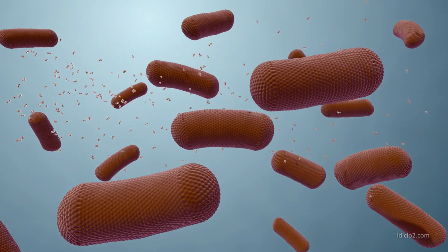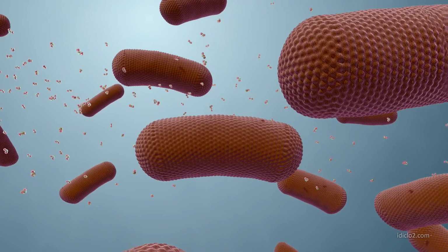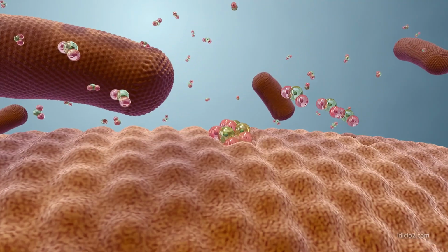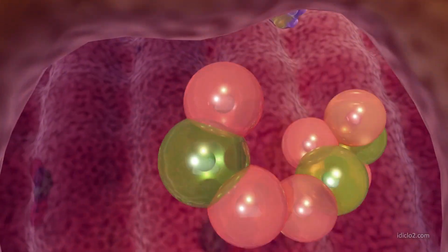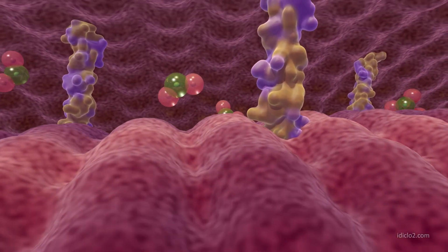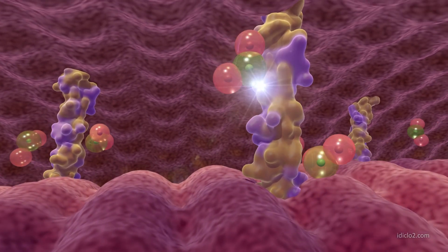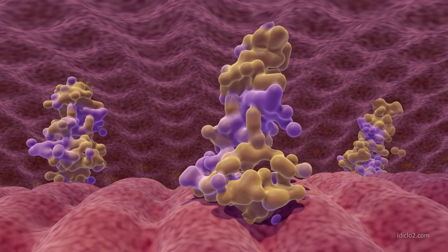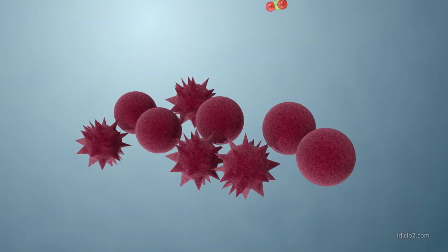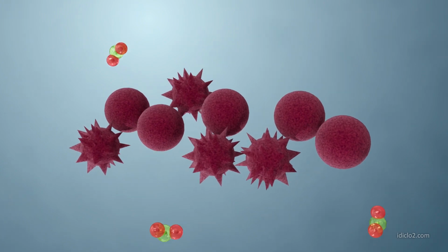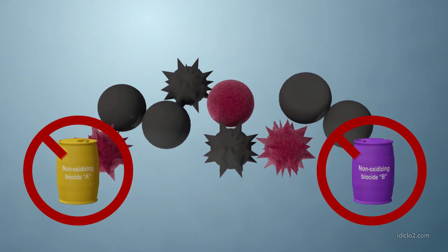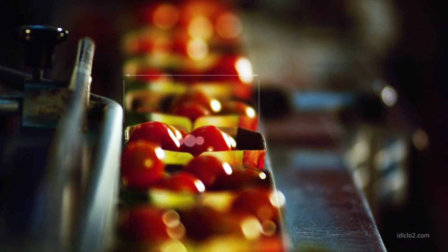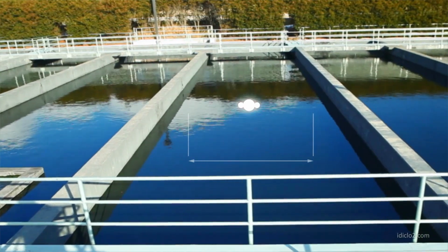When treating with ClO2, microorganisms typically found in industrial and municipal processes cannot alter their structure or develop immunity. ClO2 rapidly diffuses through cell membranes, oxidizing critical proteins and amino acids inside of the microorganism. These reactions disable cell metabolism and prevent microorganisms from developing a resistance mechanism. The use of chlorine dioxide eliminates the need to alternate biocidal chemistries in critical applications like food sanitation and drinking water disinfection.